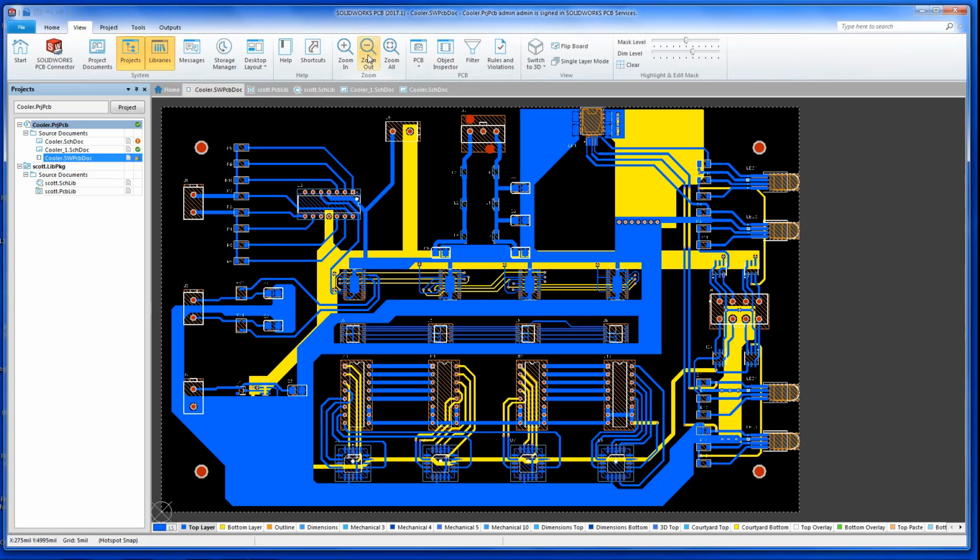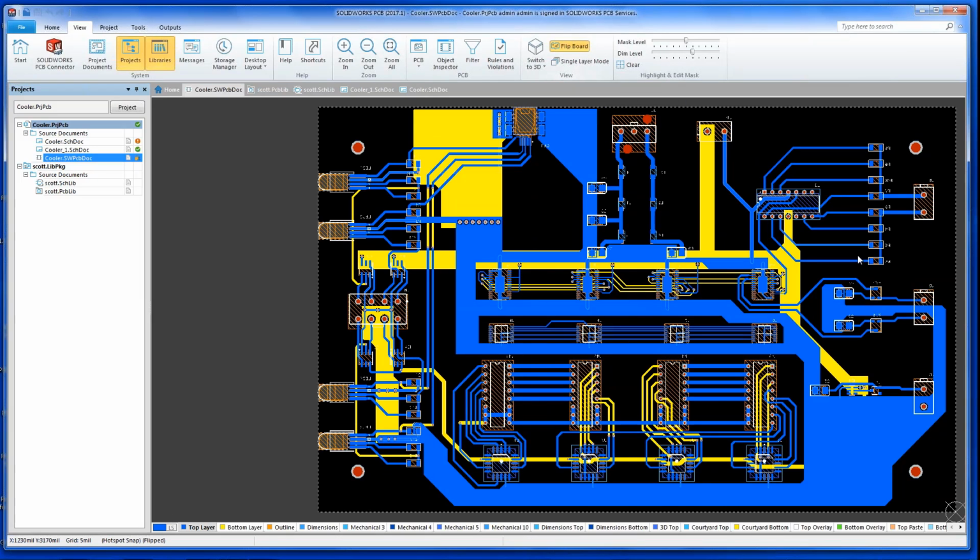The View tab is the same as the schematic. We have a nice feature in this tool. You don't see this very often in CAD tools at all. We actually can flip the board and design it from the back side. So if you have components on the back, the whole design is automatically mirrored, so you can more easily align your text and your reference designators will be properly reading left to right.